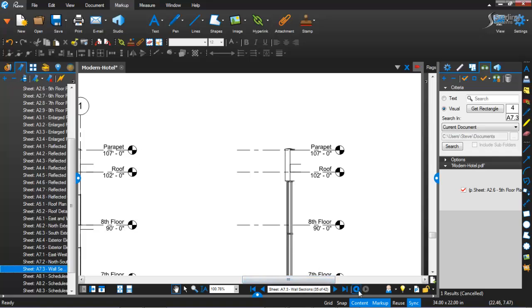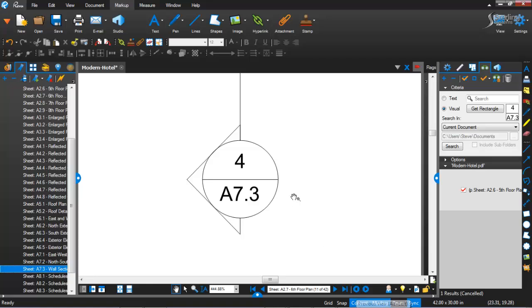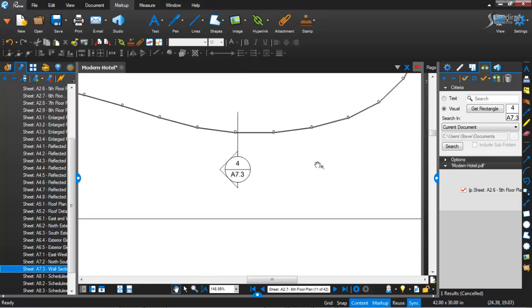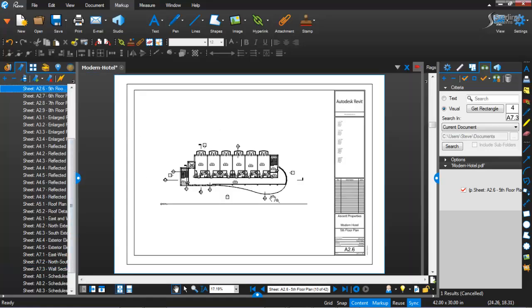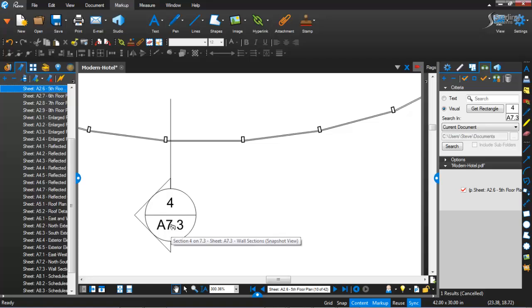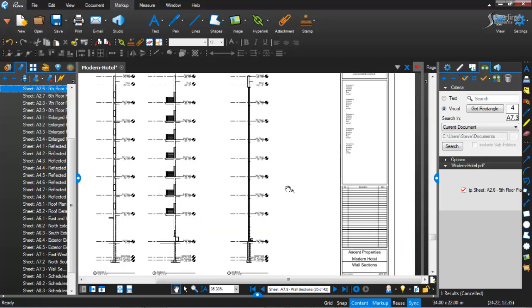Now we go back to that view, that page, and we will see that there's a hyperlink on my 2.6 sheet, since it didn't grab the 2.7 sheet. And you see my icon change there. It says an H on it. If I click on that hyperlink, it then takes me to the page. So as you can see, that can be done for anything. A hyperlink can be used to go between the same file with sheets or a different file. Pretty similar to what Revit does. So there's your part of your interoperability there.